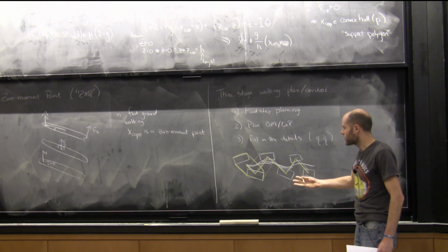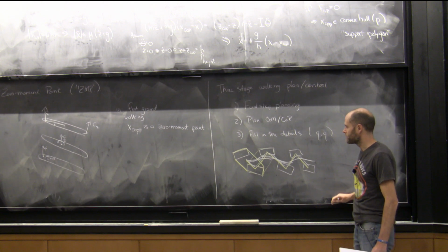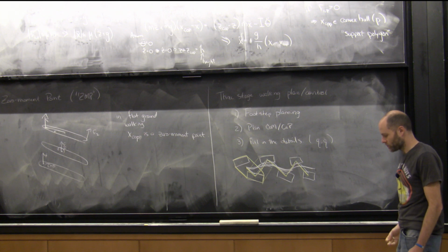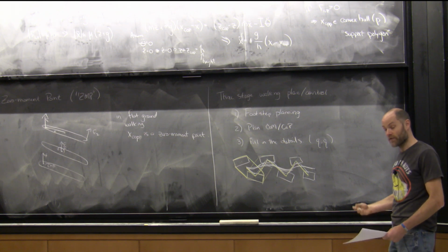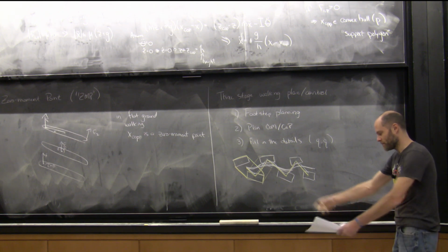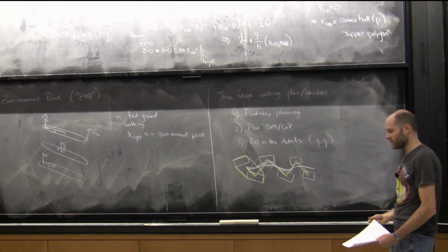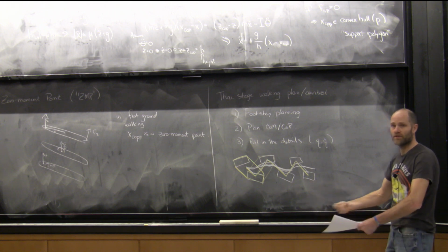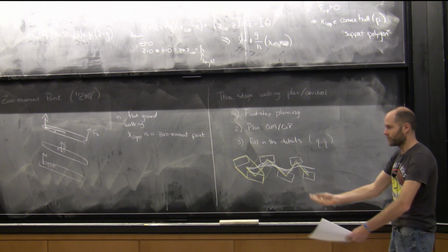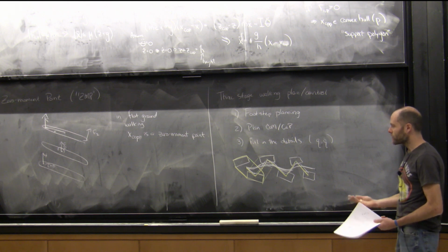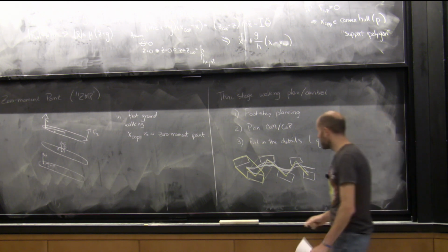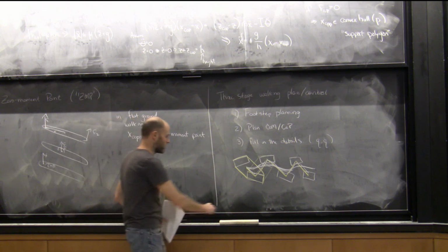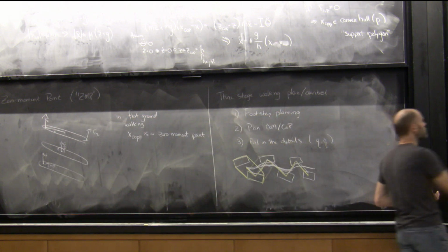Okay, so let me give you a little bit of a window into the way people do footstep planning. The simplest one is, well, there was a time when it was really thought of as an AI problem, where you would use a classical planner, throw down a bunch of possible foot positions, then try them all and see what works, and do a brute force search on it. I think we can do a little bit better now. But they're based on fairly simple approximations of what the constraints from the humanoid are.